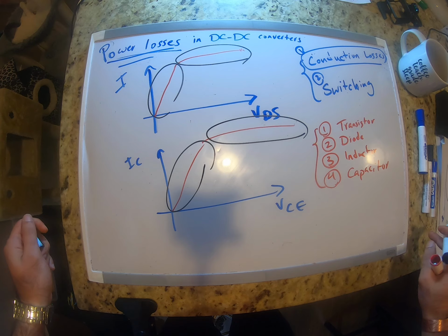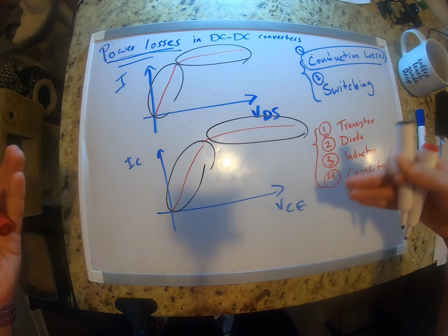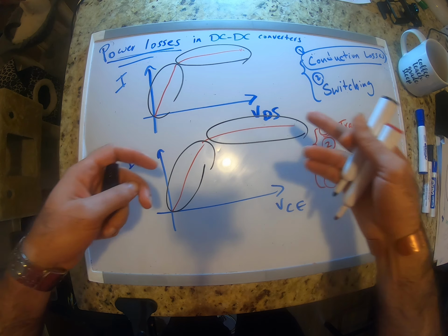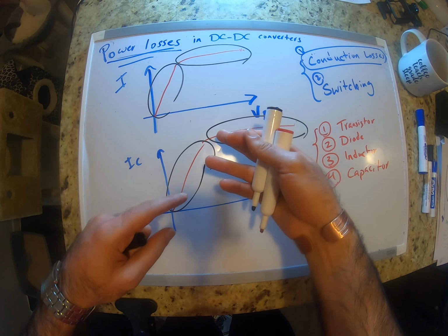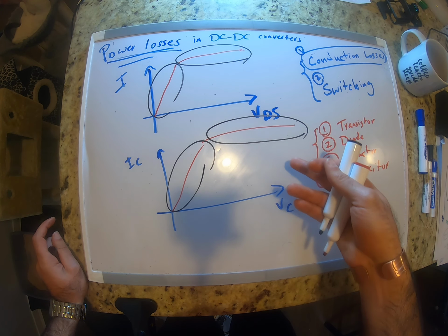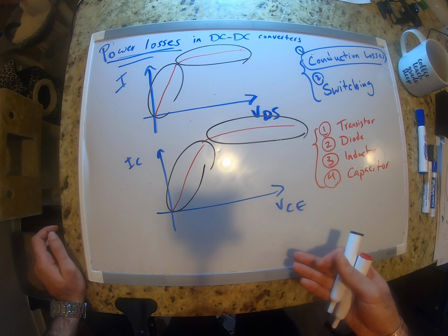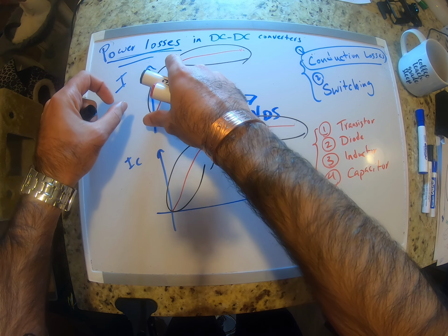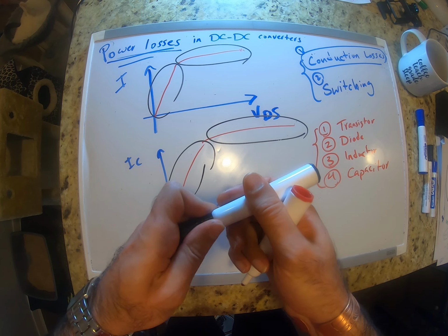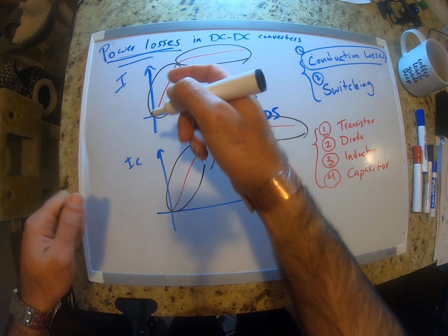In your lab, many times Andrew mentioned that your transistor is saturated, so you have to change your input voltage. That's what's happening. We don't want to operate the transistor in the saturation mode, because then there's no change in the current, so we're not using the transistor in its amplification mode. This is the linear part.